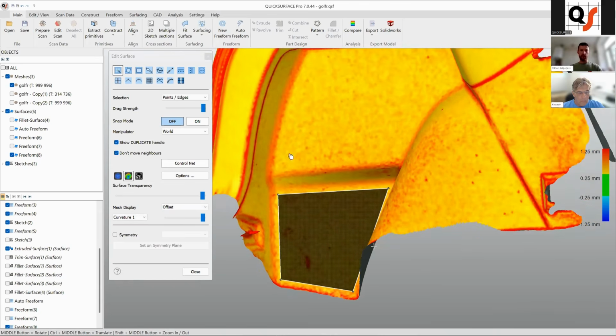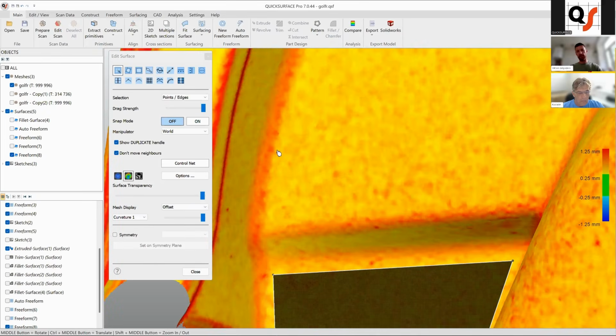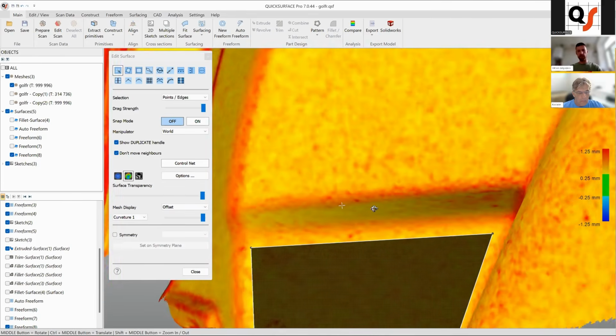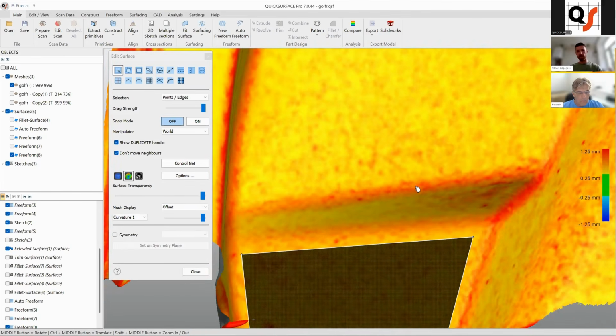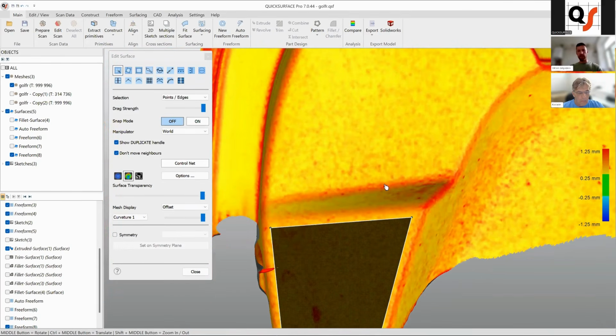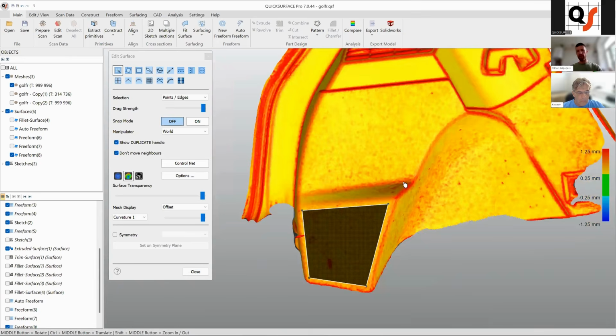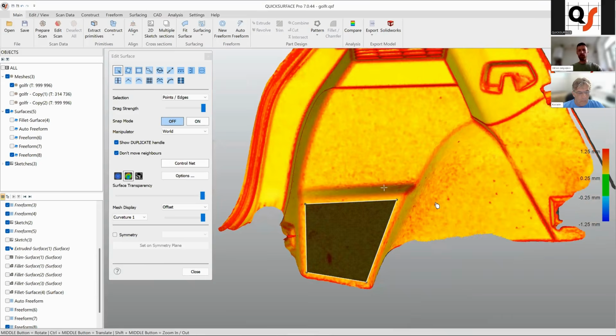So here you can see where actually your surfaces start to curve on the fillet. And it's advised not to go onto the fillet because then your surface will just start to bend already. It will be more difficult to get deviation on the last row of your quads. And same interpolation won't work that good.